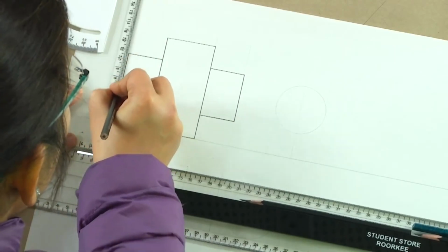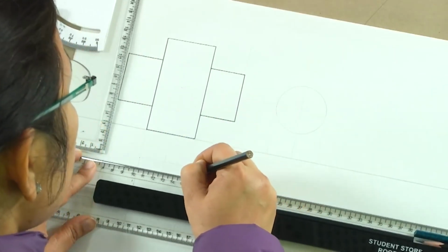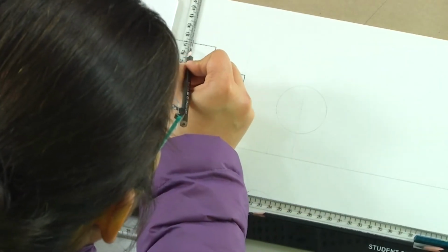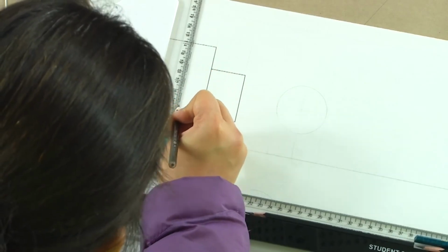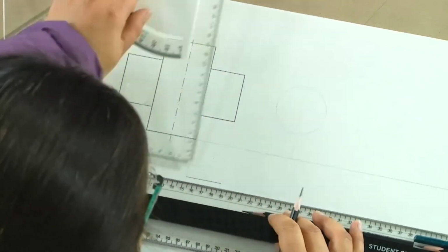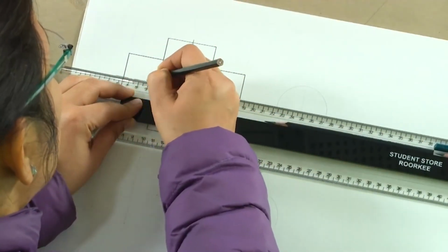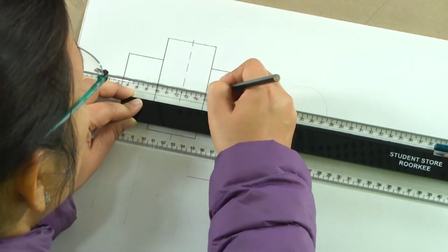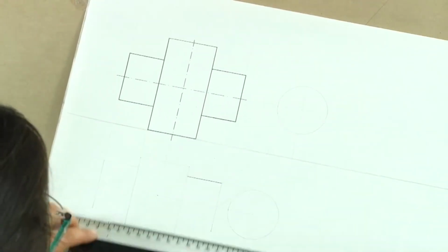In the top view, I will also make the axis as we see. So, this axis we are seeing being perpendicular to HP and parallel to VP, that is for the prism. I would advise that you should make the axis all the time, because drawing the axis helps you understand how the solids are being placed.